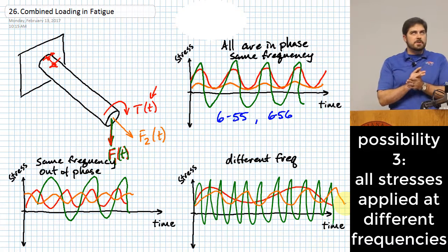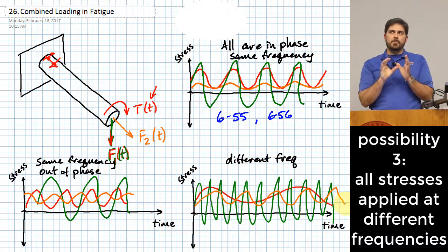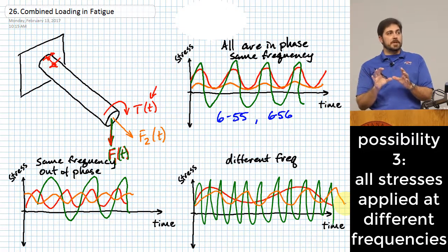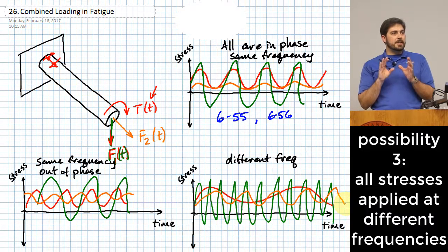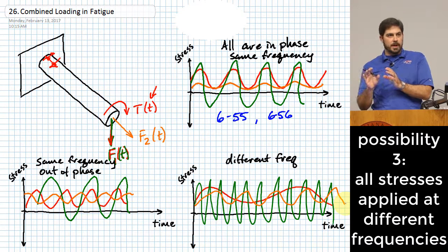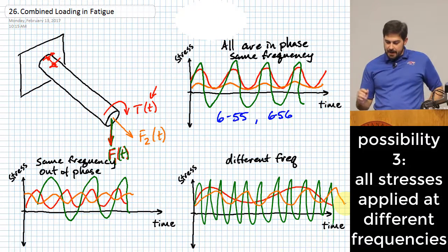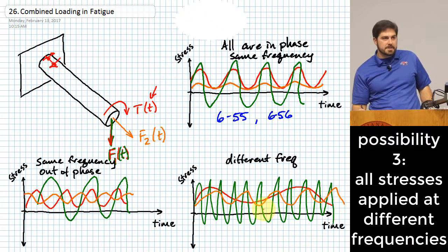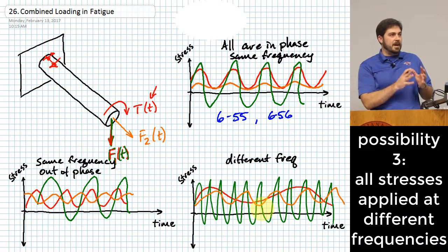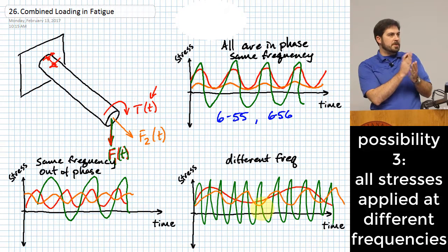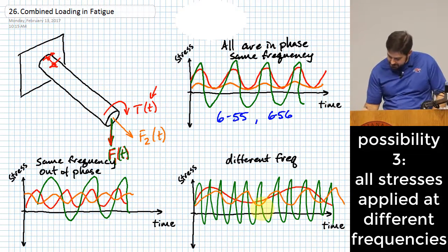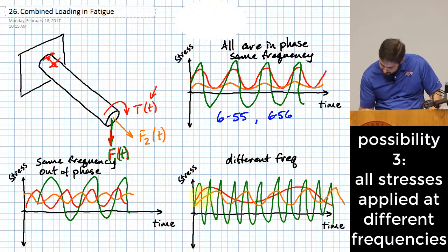Basically what you do is you say, all right, most of the time we're designing for infinite life. And once you want infinite cycles, that means you can sort of ignore the rest of this and imagine that there will be times where all the peaks do line up. They may not happen as frequently, right? So in this case, I'm trying to find a place where that might be close to happening, like maybe somewhere right in here,